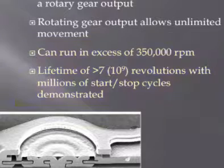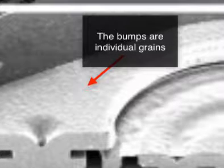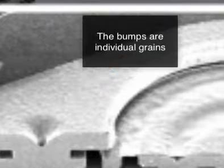Which is pretty good. And they can do 10 to the 9th revolutions before it breaks apart. Okay? So millions of start and stop cycles. Eventually they do fall apart, because polycrystalline silicon is a polycrystal. It has grains, and occasionally a grain will loosen up and tumble around inside of there.